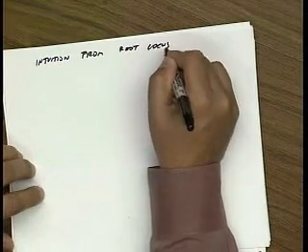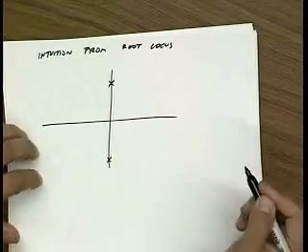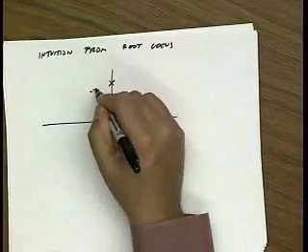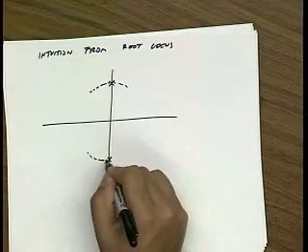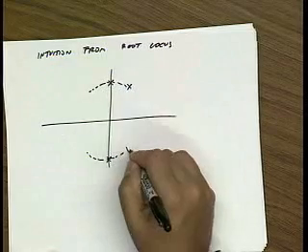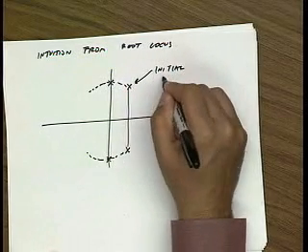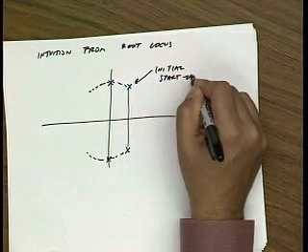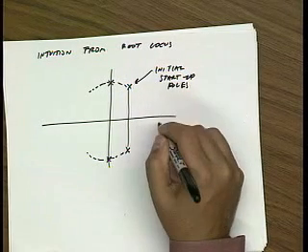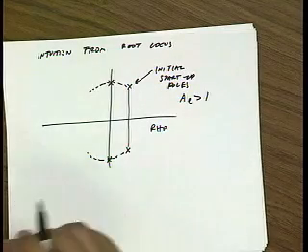So, let's use our root locus to gain some intuition. We know from our root locus that for a second order system, the poles lie on a circle, right? And our initial poles, so these are the initial poles, are in the right half plane because the loop gain is bigger than 1, right?